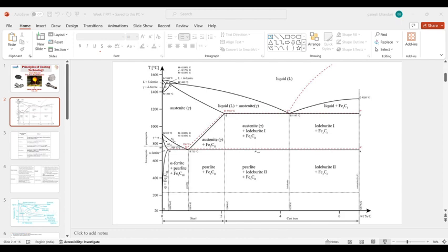Because when we talk about phase diagrams, as the carbon percentage of your mild steel increases, the hardness value will increase. Cast iron has the highest hardness values and brittle properties. So what we are trying to do, we are going with 0.4 or 0.3% carbon steel only, and providing surface carburizing to that sample. At the surface, up to some depth of 100 or 200 micron, the carbon percentage can get increased up to 1.5 or 2% or whatever amount you want.